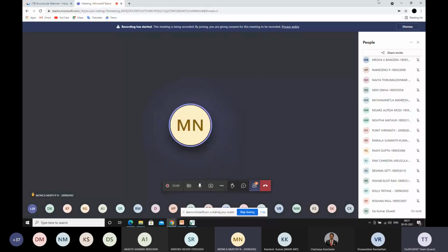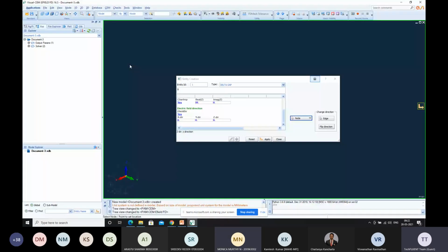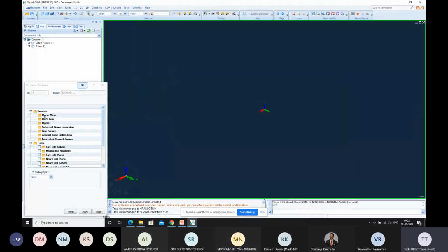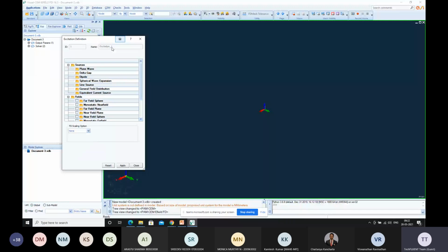Yeah, multi-source. Okay. So in SEM, you have this single excitation, right? If you click on excitation, this is the window where we'll be assigning the excitation. Multiple source is also the same window. If you're having multiple sources, today we'll go with a multiple sources example, and you will have a look at how exactly it comes up. This is nothing but your source window, the excitation window. For some cases, the excitation window will come automatically, just like what we observed on the horn antenna.